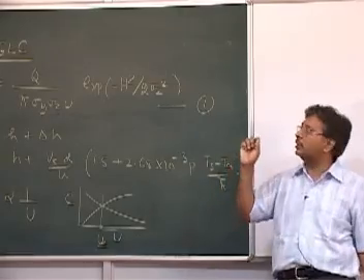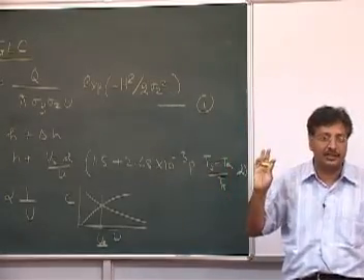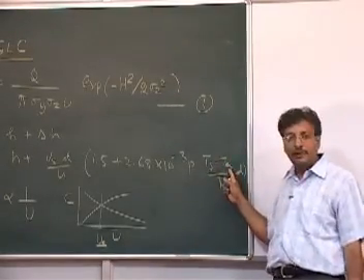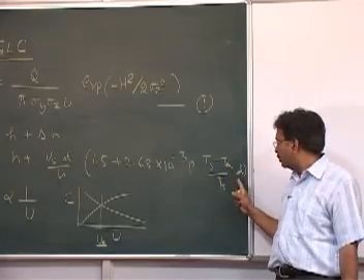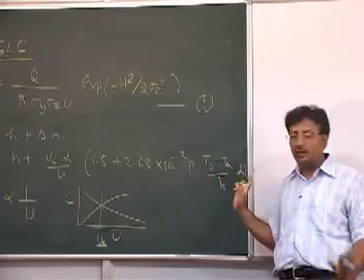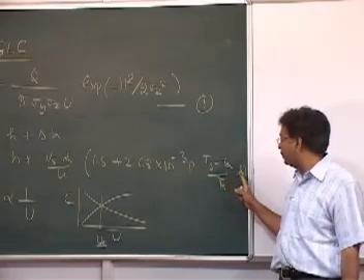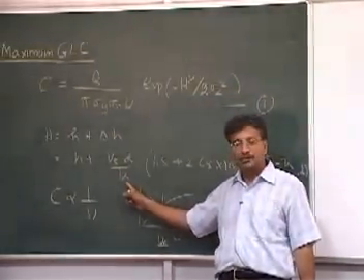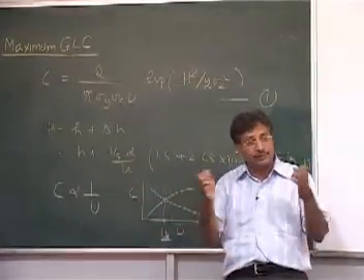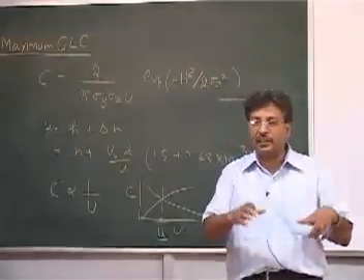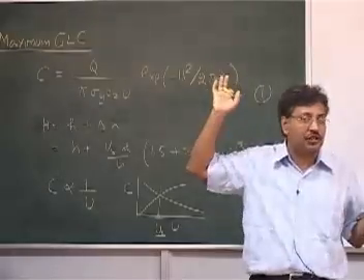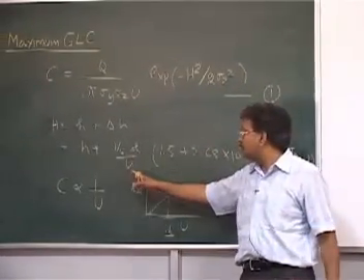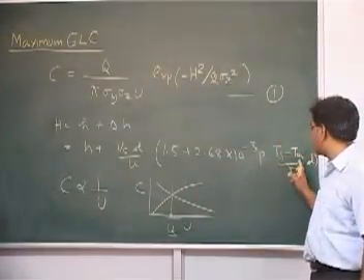This is a parameter which is fixed. They know that the temperature of the exit gases will be 100 degrees Celsius. TA could be variable. The diameter is fixed because they have designed the chimney already. Vs, the exit velocity, is fixed because they have designed their ID fans and FD fans and what velocity they are going to push the gases out with. So this is fixed. The variables are these.